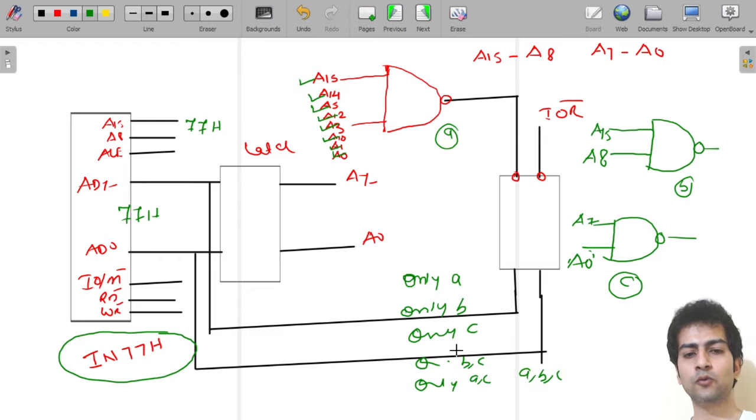You will not get more than four options, but I am just taking all the possibilities that can be there while framing the question. Most students would tick C, because they would think that the microprocessor has to deal with an input output device, and for that we only need an 8-bit address, which will come at the lower order address lines, that is A7 to A0.